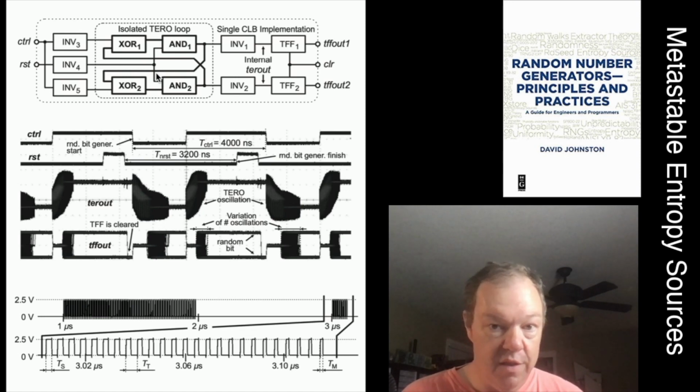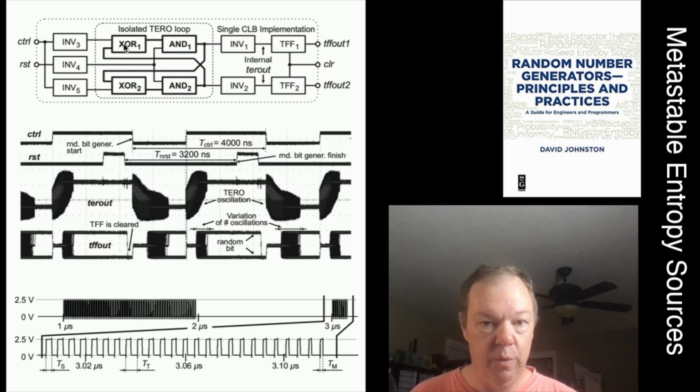And when you raise the other input to be a 1 and drop it back to a 0, the output will flip, so the other bit is a 1 or a 0. And the change they've made is to put an exclusive OR in instead of a NAND or a NOR gate. And so what happens is, each time one of the inputs to these XORs changes, the output changes. So you get a pulse which is moving around the circuit and keeps moving around and around the circuit.